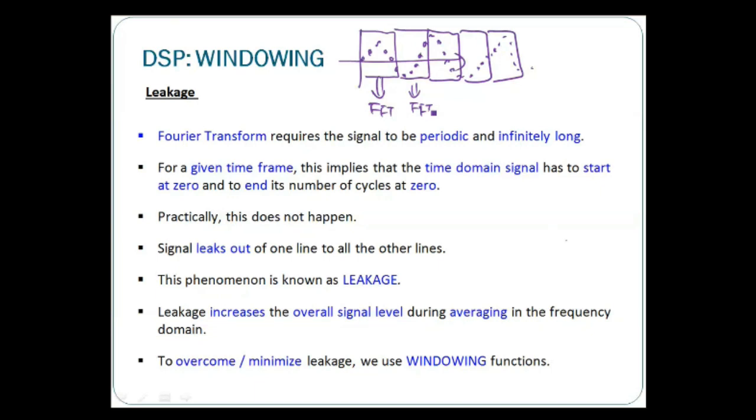So it becomes a finite length, and because it is discrete and finite, that will cause errors, especially at the beginning and the end of your signals. The Fourier transform is designed for a continuous signal that is infinitely long, where the beginning and the end are not that significant.